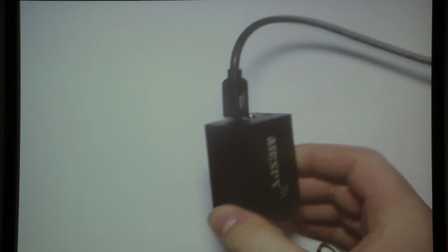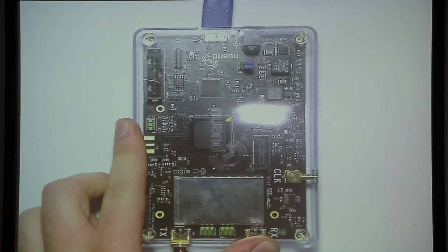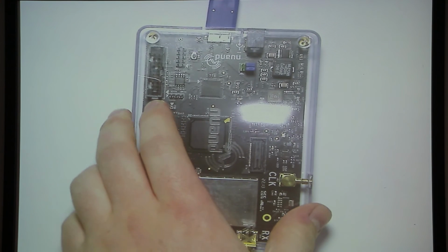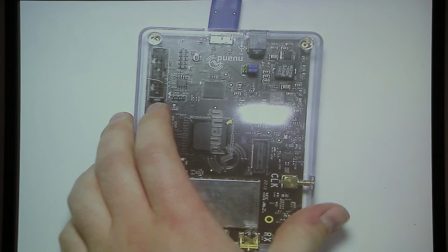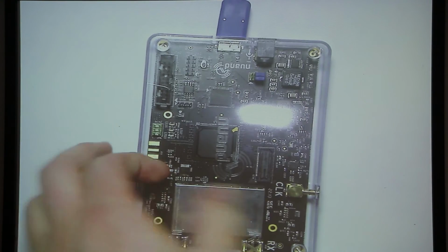There is this AirSpy, which is a bit more deluxe at receiving, but can't transmit at all, but is a little bit nicer. And then the other one I have with me is this BladeRF, which is a chunk more expensive, but much higher performance. It can do maybe 40 million samples a second, a big chunk of bandwidth. You can do Wi-Fi and GSM and fake being a cell phone base station and all the rest. Plus it can transmit at the same time as it receives, which is useful on different frequencies as well. And that costs maybe £300. And then you can spend loads more money. Fancy ones cost upwards of several £1,000s and do all sorts of terrifying things.